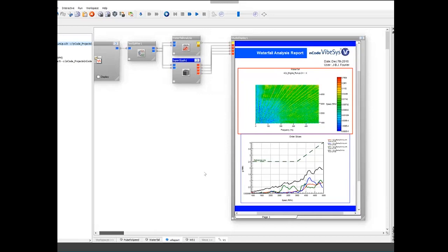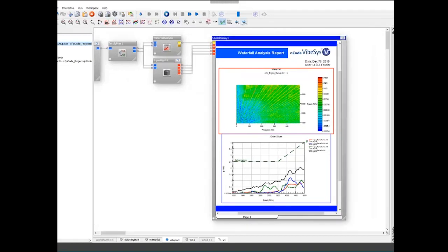I've got my report now for X, Y, and Z. So what we have below is the order extractions. I think I used 2, 4, and 6, and I put also a reference line. You could have thresholds. You know, you could have spectra that you know shouldn't be exceeded, for instance. So you can enter such a reference line by entering the coordinates of various points, and it draws a line through them. You can have different reference lines like that.